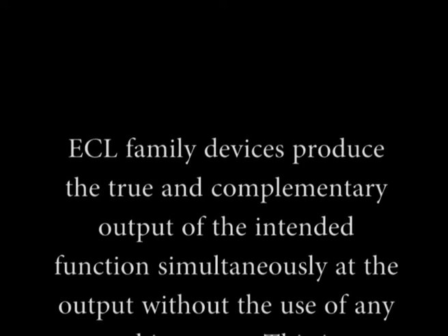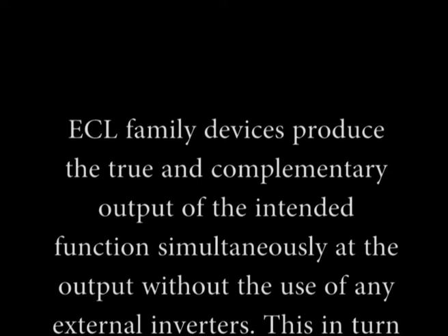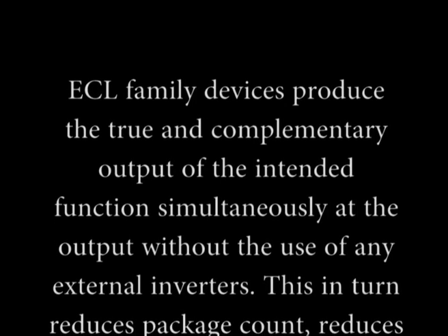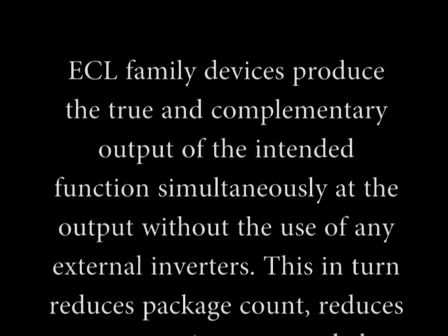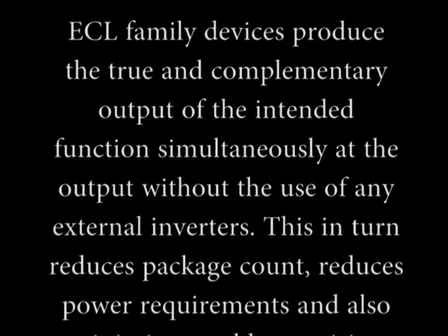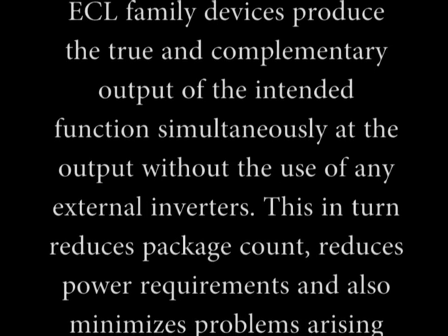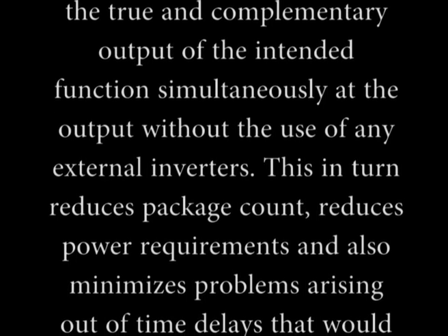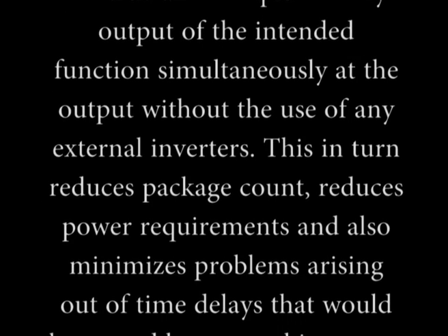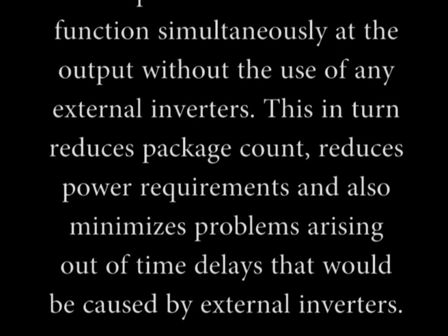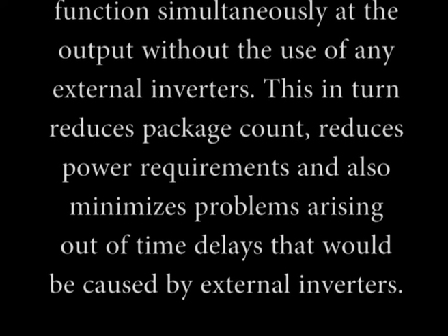ECL family devices produce the true and complementary output of the intended function simultaneously at the output without the use of any external inverters. This in turn reduces package count, reduces power requirements and also minimizes problems arising out of time delays that would be caused by external inverters.